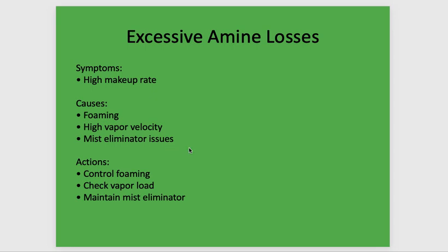All this can lead to excessive amine losses. How can you control the foaming? Check the vapor load and maintain the mist eliminator in its position, or check it.